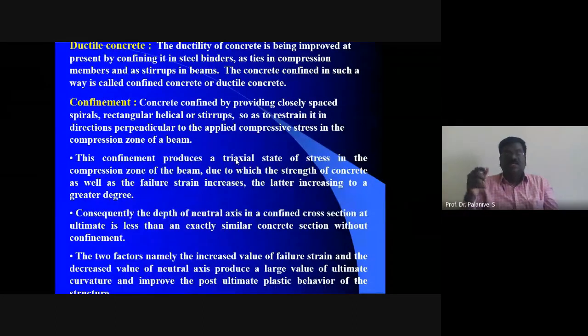Okay, if you view it, you can see another phase. Apart from the aggregate phase and the hydrated cement-based phase, there is another phase present in concrete. We call it the transition zone. In the transition zone, micro cracks are present due to its porous structure.